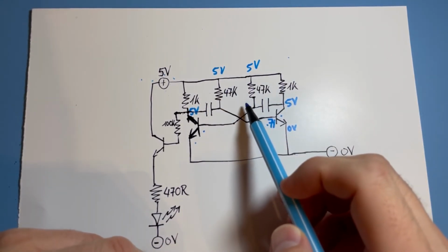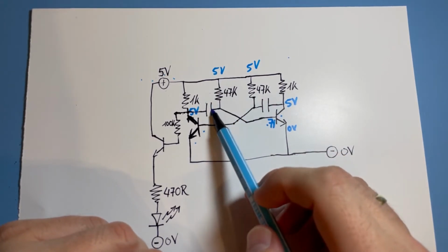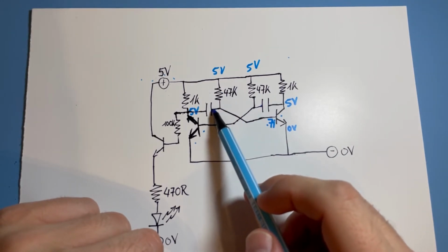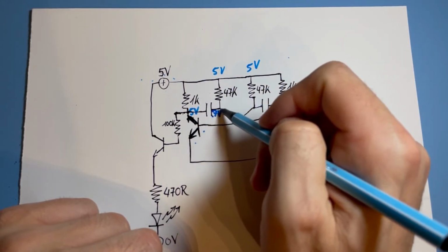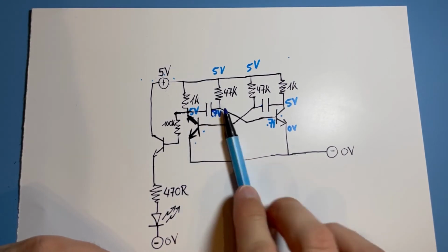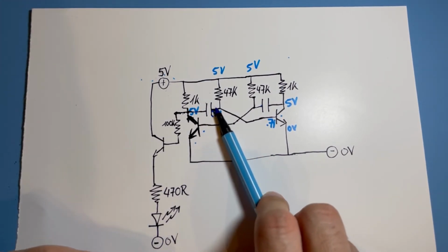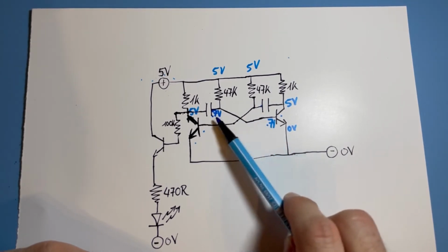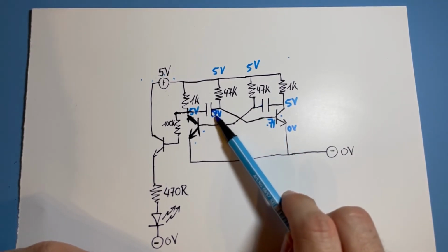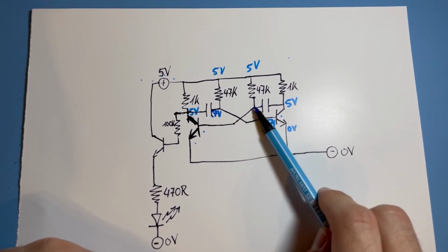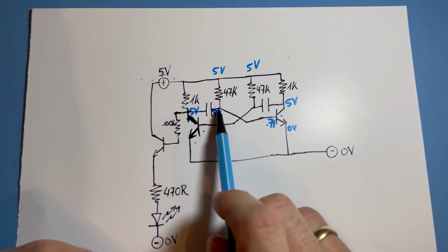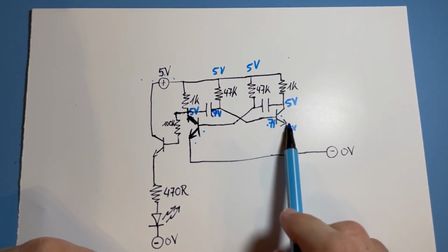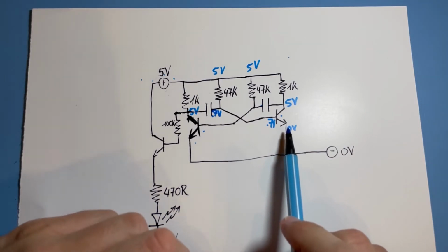And one of them is first, either this one or this one. Let's just imagine this left capacitor was loaded first with 0.7 volts here. Then the other one is at some kind of potential, but it's not quite as fast at 0.7 volt. It's below 0.7 volt because this one was first, and at this moment this one is not yet at 0.7 volt.